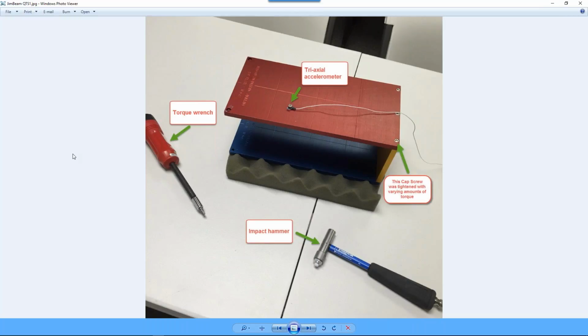We're going to use the MSS, the machine surveillance series, but functionally it's going to do the same thing. So you could think of it either way. I've got something in production, or I've got a machine out in the field and I just hit it with a hammer, and I have a triaxial accelerometer measuring response. So that's all the data that we're taking.